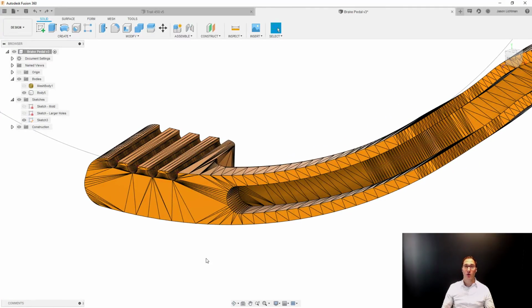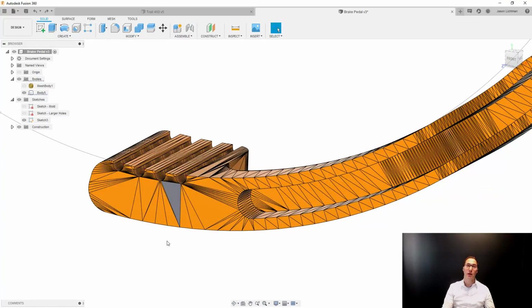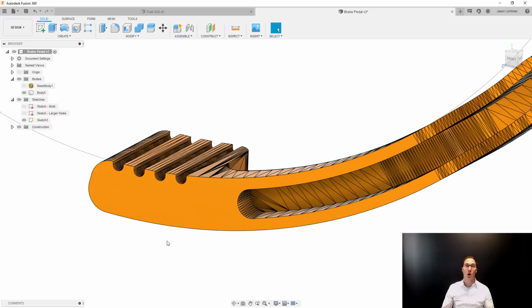This is where we had our B-Rep with a triangle for every one of our faces. So we had 15,000 of them. And what I could do here is select an individual triangle like this or this one. Hitting the delete key, it's automatically going to try to fill it in with all the surfaces that are around it. So just like that, it now turns it into a single face. The reason it's able to replace all of those triangles is because it sees the tolerance between them. It sees that they're close enough to flat that they're probably supposed to be flat, and it turns it into a flat face.